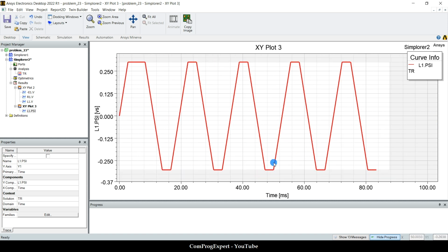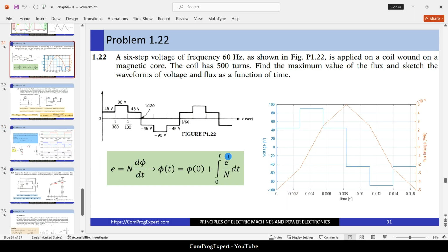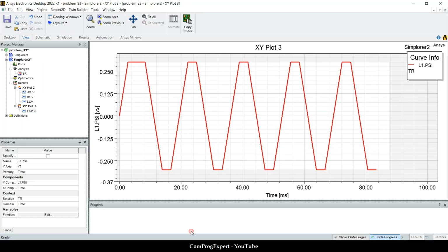Very beautiful, right? As we discussed, when we change the polarity of the input voltage, the flux linkage increases linearly up to saturation. When we have saturation, the inductor voltage becomes zero and we have current in the load. We used this integral equation to calculate the switching time.